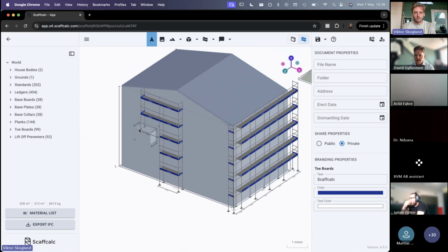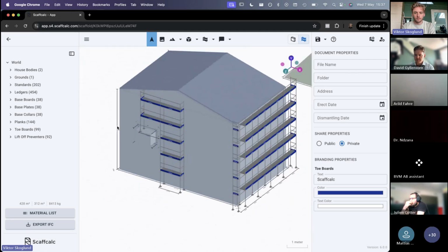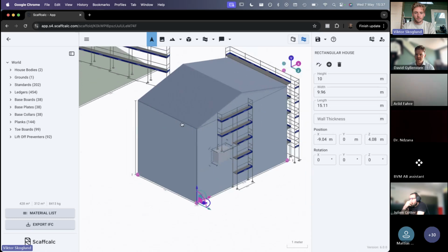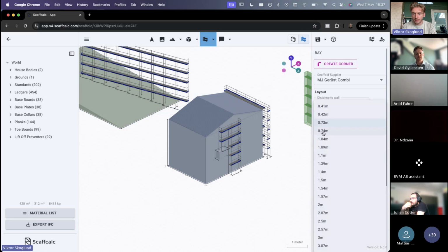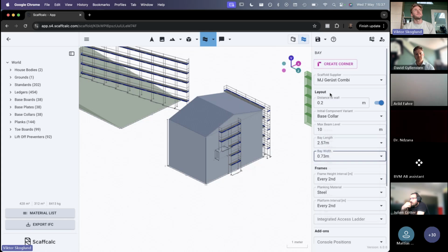Second question is, what is your approach on erecting a scaffolding in narrow alleys? Can you maybe showcase one board scaffoldings? Yes, so that would depend on the supplier, I assume. If we would pick a very, very narrow part here instead, we could pick the 042. But when I've been around in Spain and I see scaffolding, it's one standard instead of two, and then you widen the scaffolding higher up.